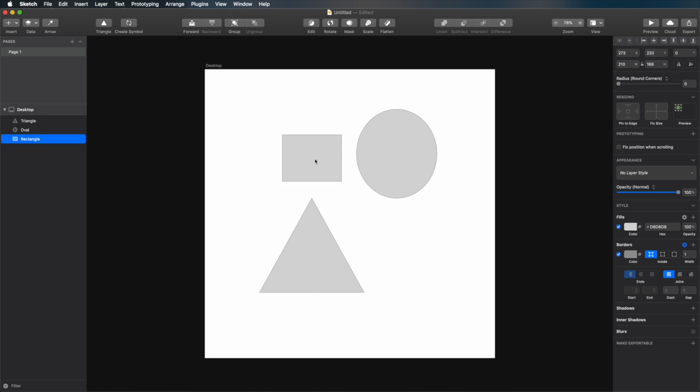So if I'm gonna nudge this up, I can press Option on my keyboard, hover with my mouse cursor on a specific element, and then I will get measurements from the edges of my element to the element I'm hovering on. And this is actually super, super helpful.